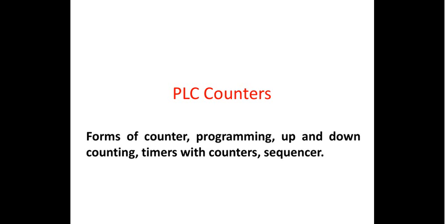Let us say that a particular crate has got the capacity of 100 bottles, right? So after the 100th bottle is packed or sealed, it is put into the crate. So there should be a deflecting mechanism which should take away the crate which is full, and it should make one more crate to come in. So that process might take some delay. After 100 bottles are filled up, you may have a small delay of 5 seconds before the next crate is positioned and the packaging starts.